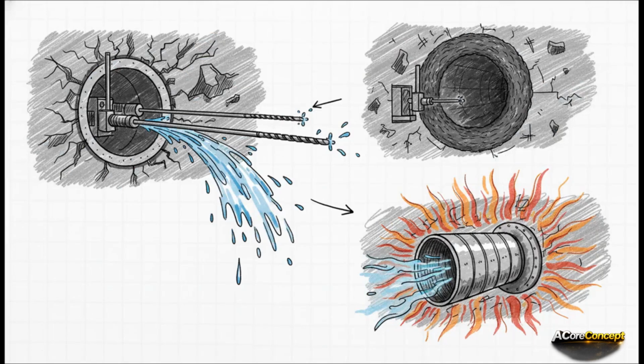To counteract massive hydrostatic pressure like that, you have to proactively manage the water way before your excavation reaches it. We're talking drilling pre-drainage holes to relieve pressure and doing advanced grouting to create a reinforced impermeable shell around your future tunnel path. Plus, the Himalayas sit right on top of a highly active geothermal belt.